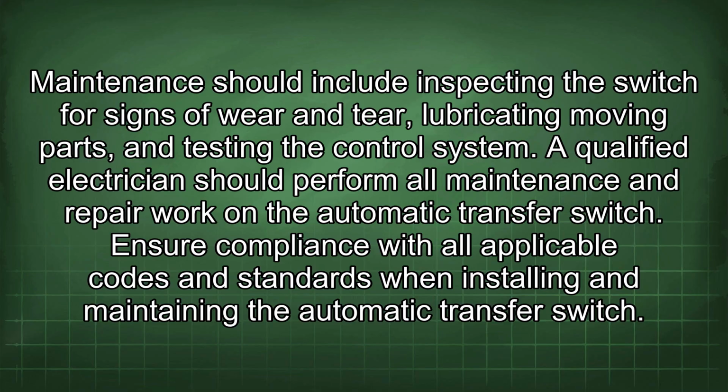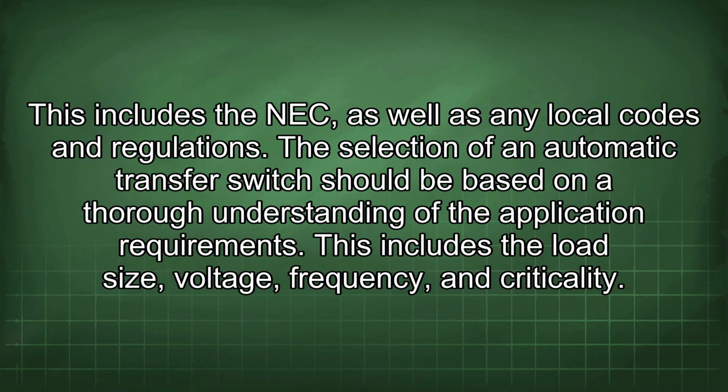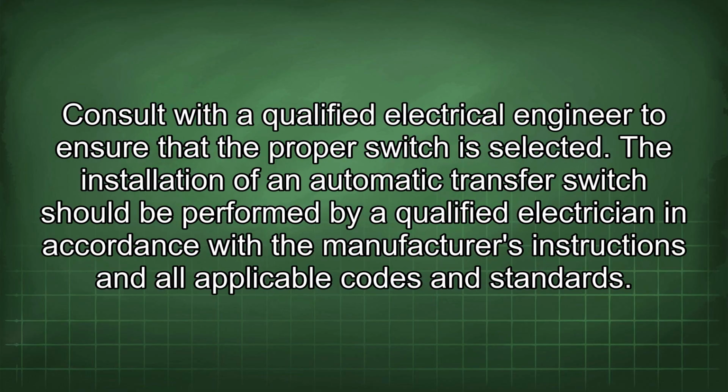Ensure compliance with all applicable codes and standards when installing and maintaining the automatic transfer switch. This includes the NEC, as well as any local codes and regulations. The selection of an automatic transfer switch should be based on a thorough understanding of the application requirements. This includes the load size, voltage, frequency, and criticality. Consult with a qualified electrical engineer to ensure that the proper switch is selected.